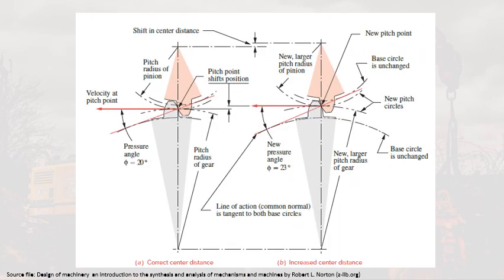When involute teeth have been cut into a cylinder with respect to a particular base circle to create a single gear, we do not yet have a pitch circle, because the pitch circle can only be formed when there is a meshing of two teeth. The pitch circle only comes into being when we mate the gear with another gear to create a pair of gears, which we call the gear set.